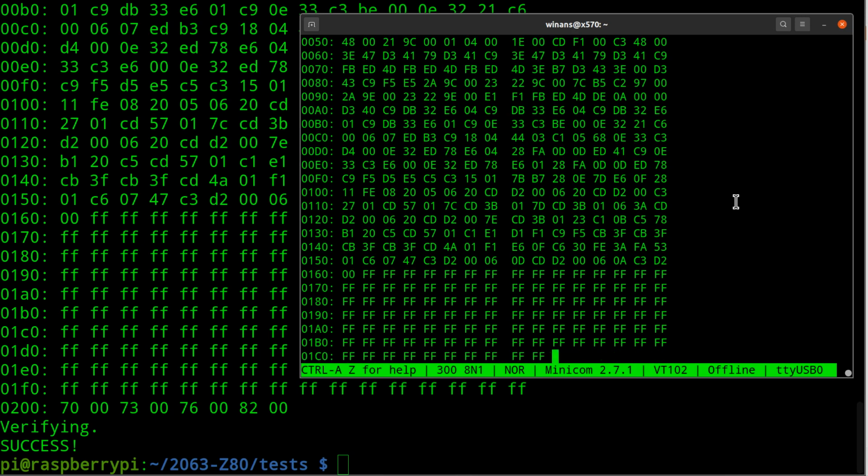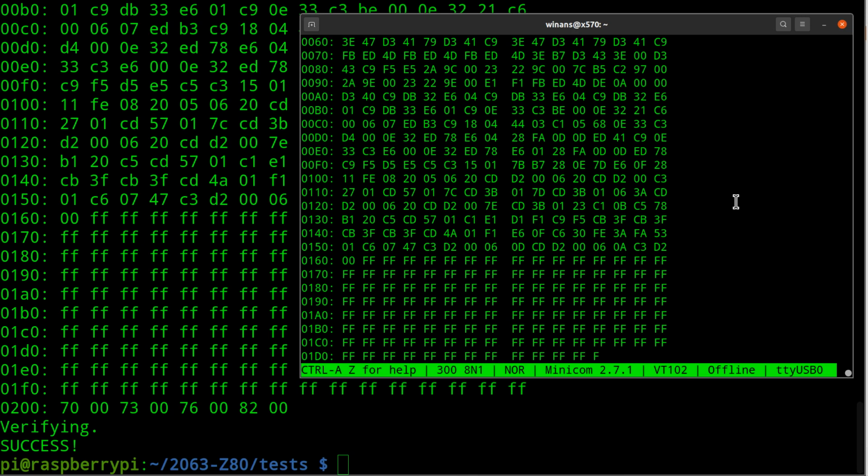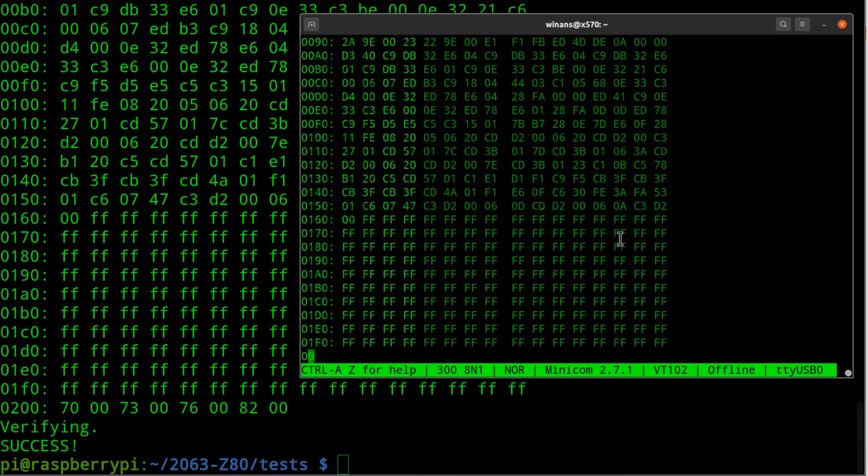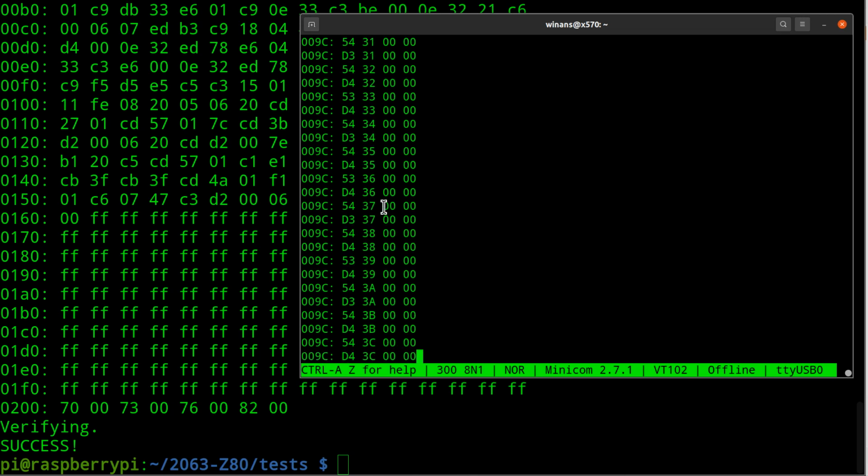Anyway, this is 300 baud. We probably should have commented out the dump part of the program, because this is just an eternity. Be that as it may, the point of the whole thing is to run this slow enough that we're getting multiple interrupts while the thing is printing and it can't even keep up. Look at these values in here. It's certainly not multiples of 40 in hex over here, right? What are the values? We got 54 and D3 coming out of here.